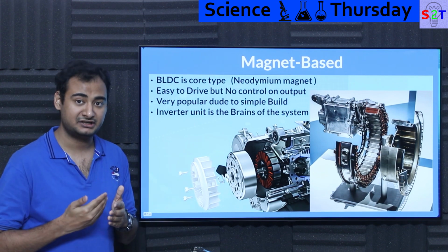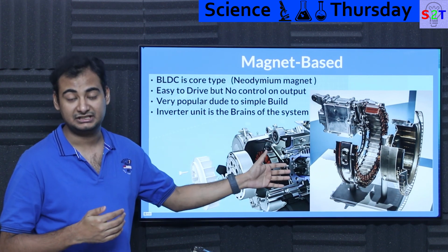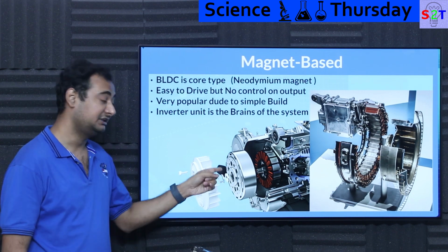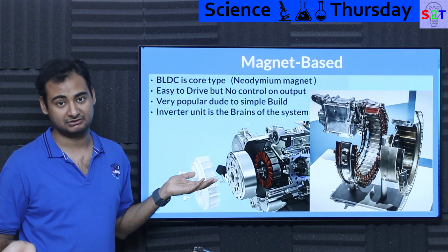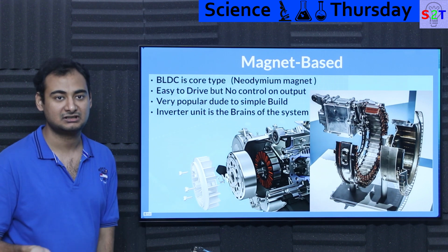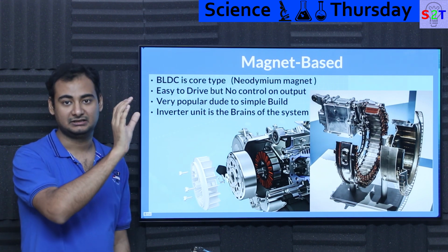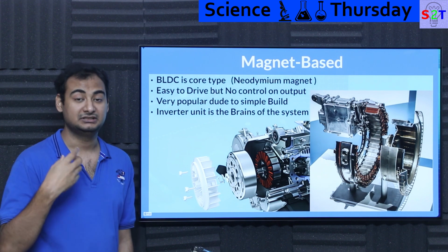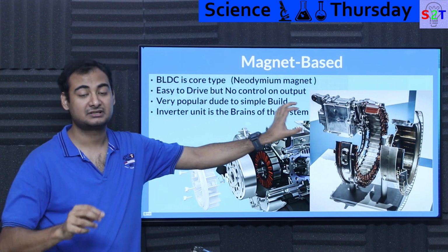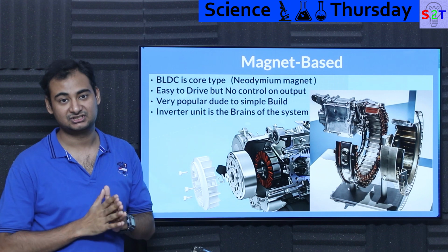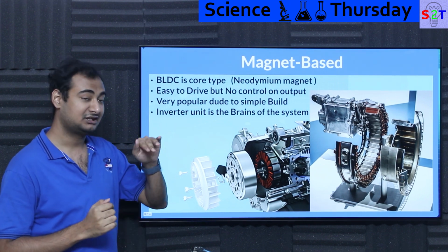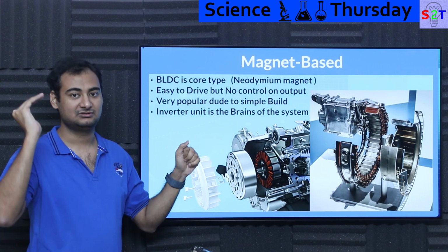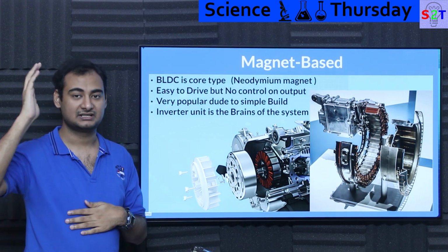If you are using it as a generator and it's directly connected to, let's say, your engine shaft, or, say, in a two-wheeler system, the RPM range creates an issue where it will create whatever it wants to create. Of course, there will be a power graph you can look at: at this RPM I'm producing this, at this RPM I'm producing that. That does mean the inverter unit, the controller circuit that you are putting in, has to be much more robustly built so it can handle much higher voltage. Even if the output voltage is locked at, let's say, 13 volts, the input voltage could easily go from, let's say, as low as 10 volts to as high as 100 volts.